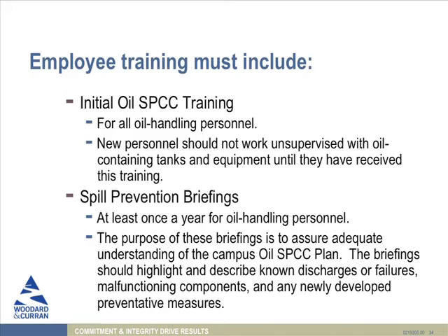So training. There is a training requirement in this program. All oil handling personnel have to have initial oil SPCC training. And anyone who has an oil handling role really should not work in an unsupervised capacity with oil containers until they've had it. Now, what is an oil handling personnel? It's anyone who is dispensing from or filling any of your tanks or containers, including kitchen grease. It's anyone who is maintaining the tanks, doing inspections of the tanks, anyone who's going to be responsible for responding to a release, who has a responsibility written into your oil SPCC plan. All of these folks should have oil SPCC training. It is a one-time training requirement.